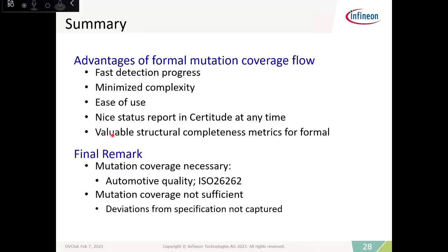But finally, it must be emphasized that even 100% mutation coverage does not guarantee that the design has been fully verified against the specification, which is impossible until you have a fully formal, unambiguous specification, which in reality is unfortunately not the case yet. On the other hand, 100% mutation coverage provides good confidence that at least each part of the design has been addressed to considerable depth by the verification.